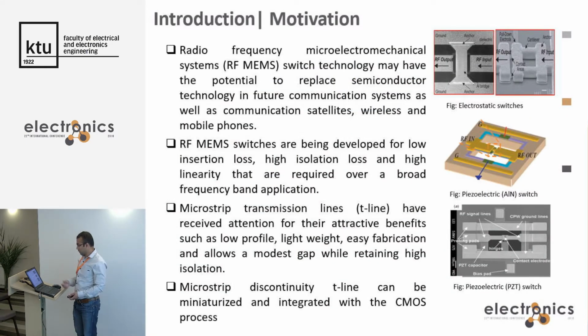So RF MEMS switches: here we can see some kinds of switches, based on electromagnetic, piezoelectric, and also electrostatic actuation. With the switch, we also need to integrate the transmission line. So this study is basically about the integration of the RF switch with the transmission line, which is a microstrip transmission line.